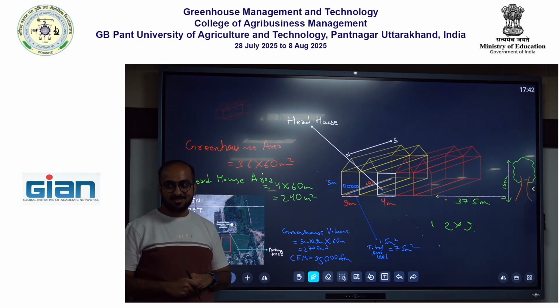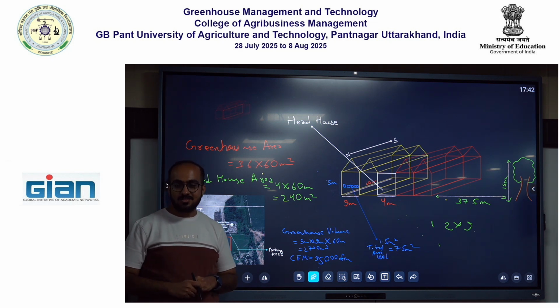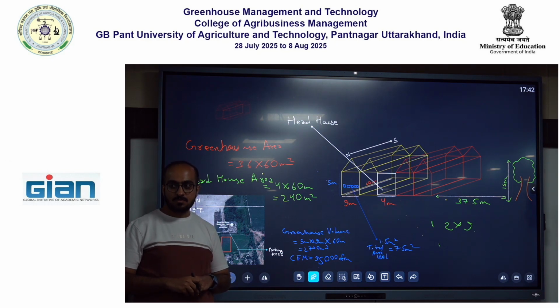5. Yes, sir. So it's okay to put fans, but remember electricity costs are one of the considerations. So you can calculate how much it's going to cost for those 5 fans. The same company which gave you specifications will also tell you the power consumption, how many watts each fan uses. From that watts you can calculate kilowatt hours.